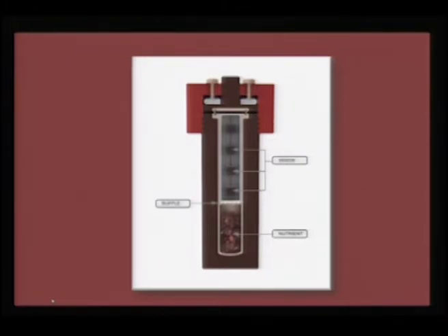And typically the process that occurs is shown here. Those big blocks of quartz are actually precipitating on this seed crystal which is kept here, and this is being pulled upward, say 1 millimeter per hour or 1 millimeter per 2 hours, that is the rate at which it is slowly done. Therefore, it runs into several days and months before the whole thing is actually pulled out.